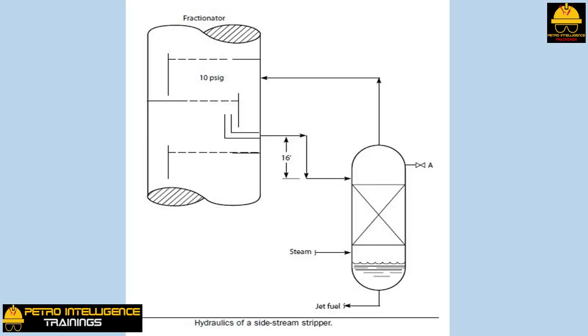The particular problem he encountered is illustrated in the picture. The jet fuel product was steam stripped to remove a lighter naphtha contaminant. But much naphtha was left in the jet fuel. Apparently, the packing in the stripper tower was not working properly. However, a discussion with the unit operator indicated that they were using very little stripping steam. Introduction of a normal amount of steam resulted in a loss of liquid level in the bottom of the stripper.